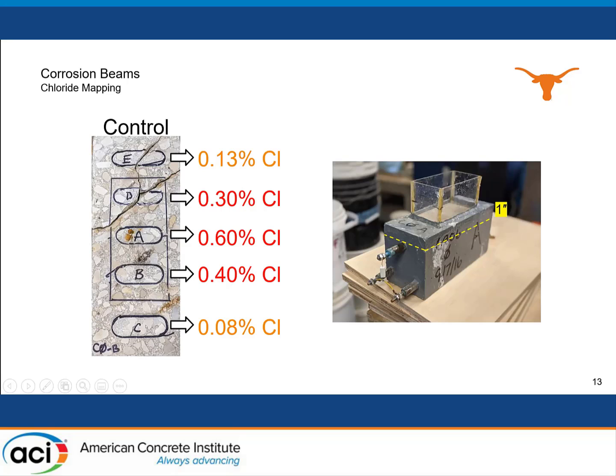And we see that outside of the perimeter, I'll backtrack a little bit. These numbers are so high, it is assumed because of localized cracking. So once you have localized cracking, again, chlorides have a free pass and it is not diffusion based. In the outside perimeter, we're assuming that this is diffusion based, and that's why we have more moderate chloride levels.